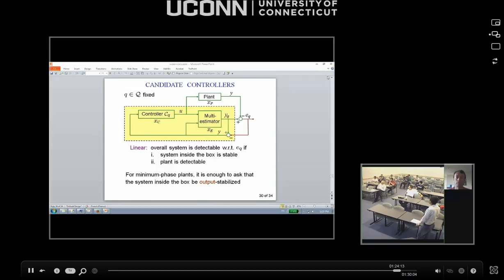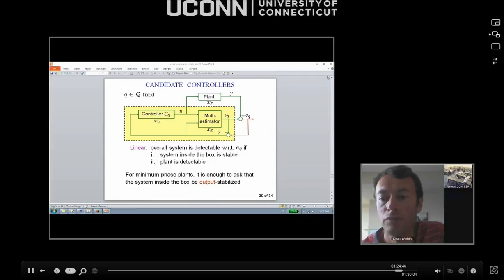I think there is a proposal that you guys can do by merging these ideas with maybe the MPC type thing for the controller design. Your research question is what is the minimal set of controllers and estimators that you need to switch among. One nice thing about this is that as long as you have detectability, your error is going to go to zero with this, right? Correct by design. The first thing we should do is maybe type MPC and supervisory into Google and see if somebody has already looked at MPC controllers, because we have them.